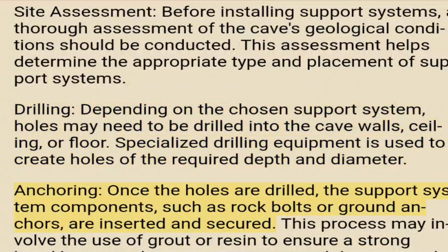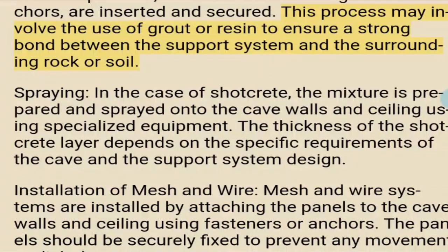Anchoring. Once the holes are drilled, the support system components, such as rock bolts or ground anchors, are inserted and secured. This process may involve the use of grout or resin to ensure a strong bond between the support system and the surrounding rock or soil.